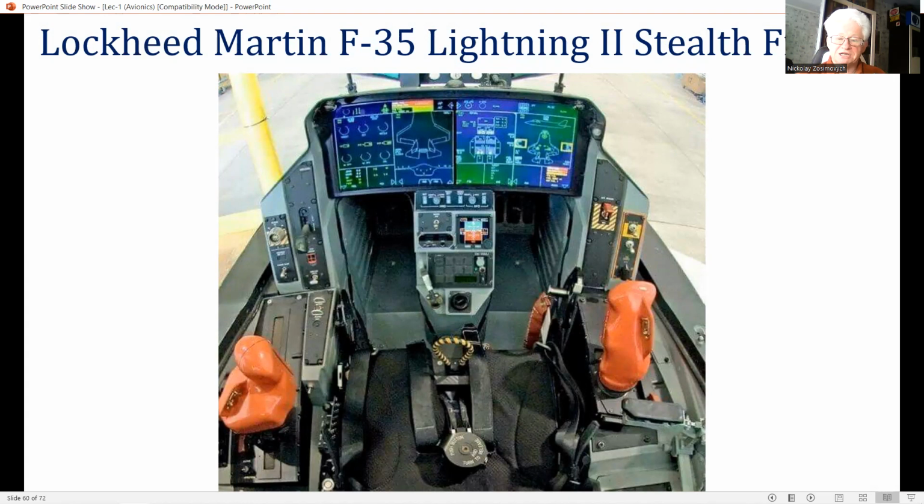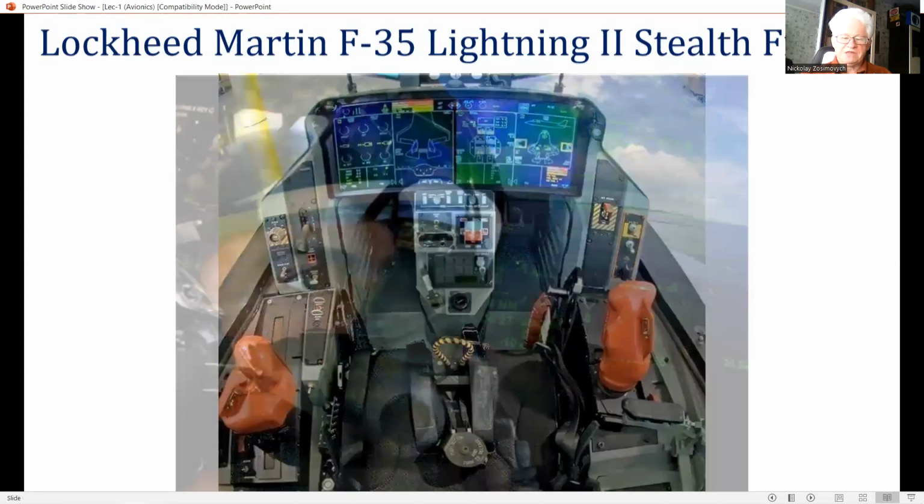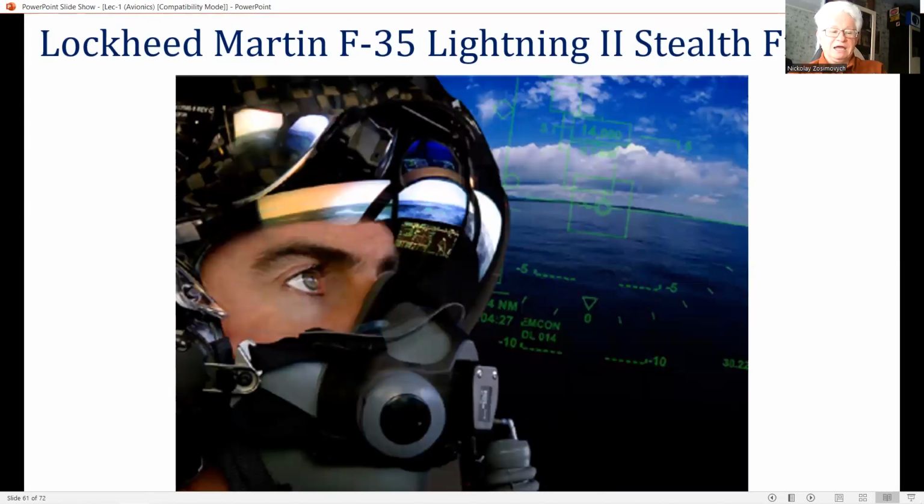The high-integrity FBW flight control system compensates for the lack of natural stability and provides excellent control and handling across the flight envelope and under all loading conditions. The F-35 pilot is equipped with a sophisticated binocular HMD and sighting system, which is shown in this slide.